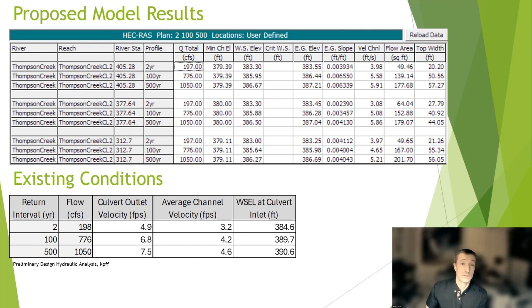The 100-year model shows that the water is confined within the banks of the new channel, so there is no anticipated scour around the abutments of the proposed bridge either. Furthermore, since the average velocity of the proposed stream bed is close to the existing stream velocity, the migrating fish will have little trouble navigating the new passage unless there happens to be a flood event.